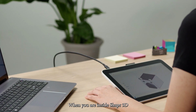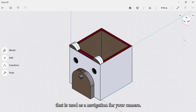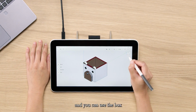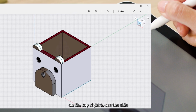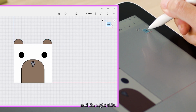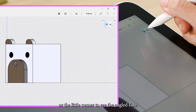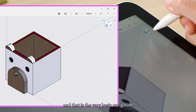When you're inside Shapr3D, you can see a little box on the top right that is used as a navigation for your camera. This is the view by default when you come into Shapr3D. You can see the X, Y, and Z axis right away. And you can use the box to either tap looking at the front or tap on the sidebar of the cube on the top right to see the side, and then right side, top side, or the little corner to see the angle side. You can also use the little arrows to rotate, and that is the very basic navigation in Shapr3D.